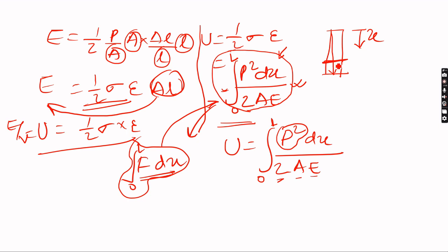up to this, and because of that weight, how much deflection is coming or strain energy is stored. So up to this part, if you make a free body diagram, below this line, whatever mass is there, due to that mass only, this body will be extended. This body has also some mass, but at this point, only this mass is exerting some force. And that force is nothing but the mass of this into g. Suppose this is M1. So M1 into g will be the cause. This force will create some deformation in this body or strain or strain energy. This force will be the main reason for this.